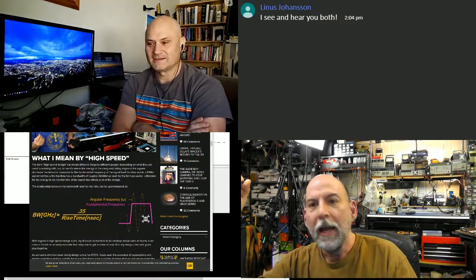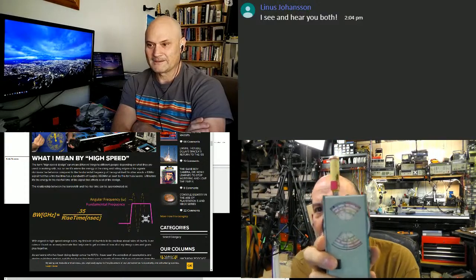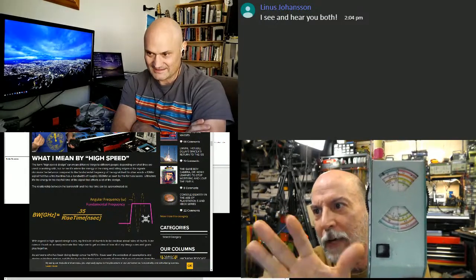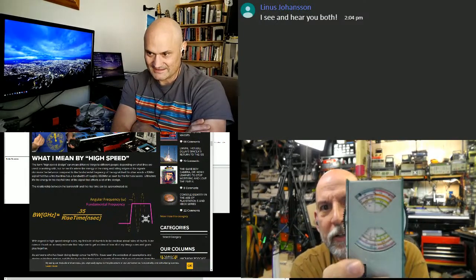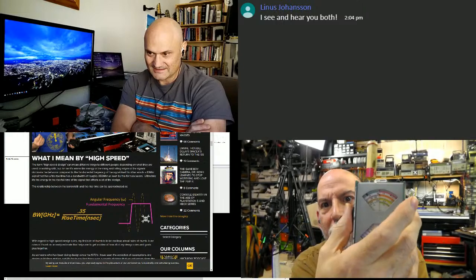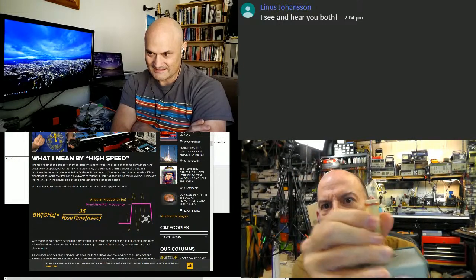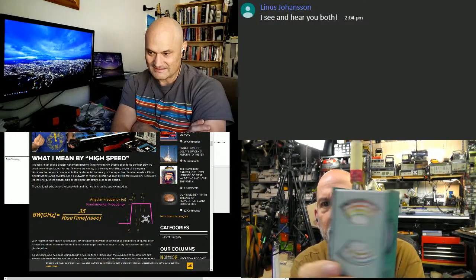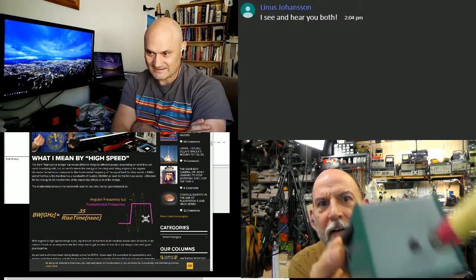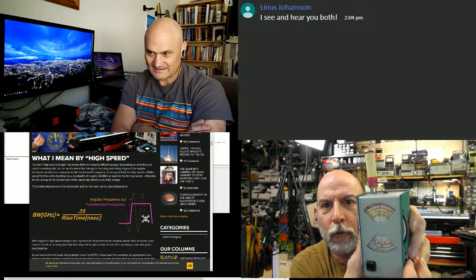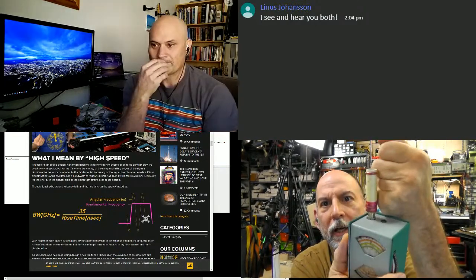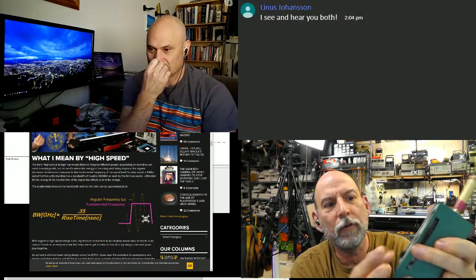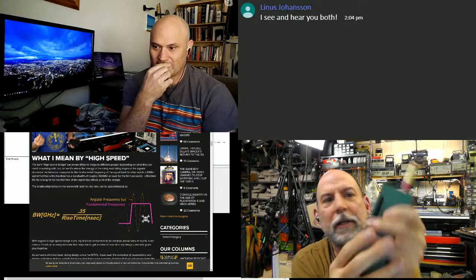Yep. Hey, you talk about oscillations. Here's how I learned oscillations and energy, and you talk about that vibration of a spring. This is a grid dip meter, which is basically a tunable C and an L, which I can put on here, a coil. And I have a whole selection of coils. And I went around testing everything. I'd see what frequencies it absorbs. You can put this up to a coil and figure out the value of the coil or the tank circuit next to it by tuning and watching the meter dip. It's a grid dip meter.